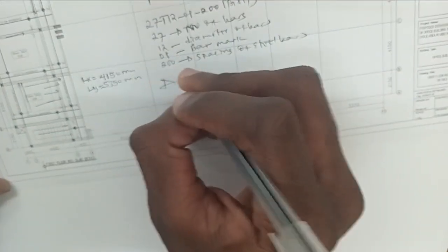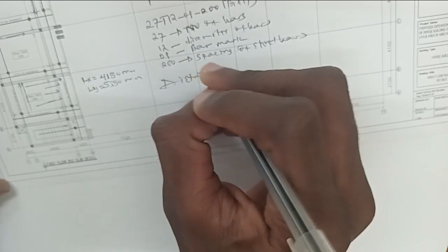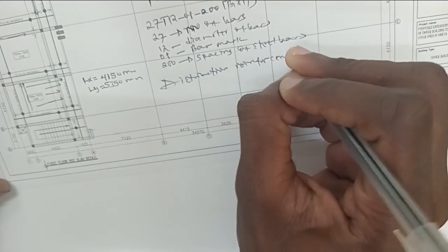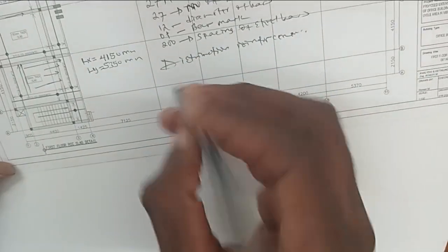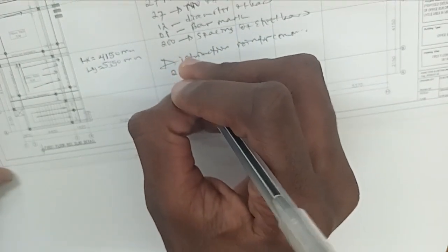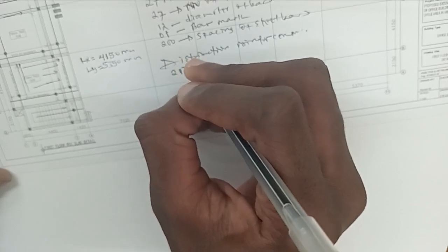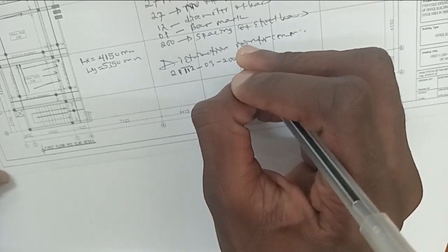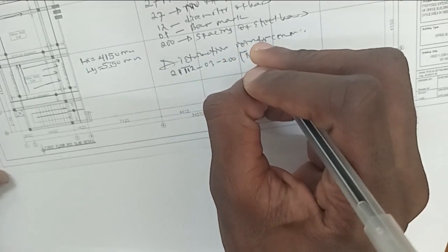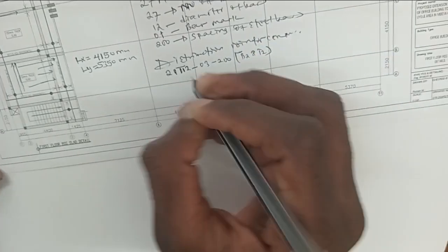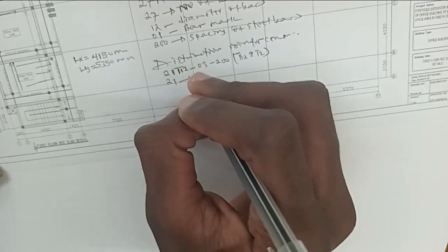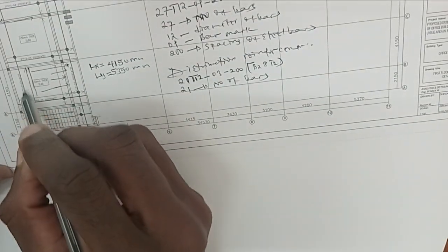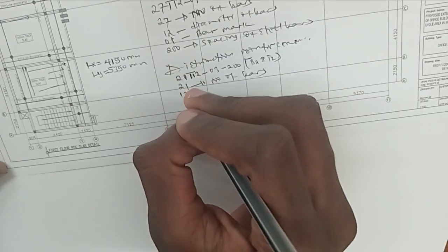And let's see, here is the distribution reinforcement for this slab panel. Now, its detail shows there should be 21 bars with a diameter of 12 at bar mark number 3 with a spacing of 200 millimeter, B2 and T2. B2, this 21 is the number of bars required at this slab panel, and this is 12.